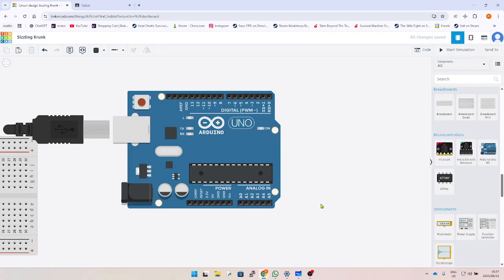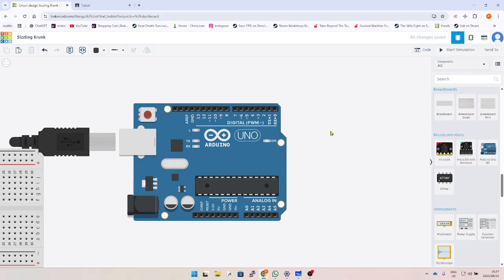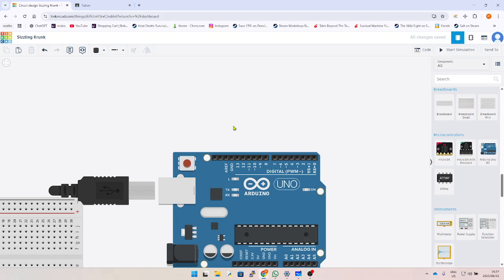Now, this device specifically has 14 digital pins, as you can see here, from 0 to 13. Digital meaning it either outputs 0 or 1, input and output 0 and 1. Now, my Arduino is not here today, so I can't show you, but this pin can output a 0 or 1 or take an input of a 0 or 1. That's what digital input and output means.